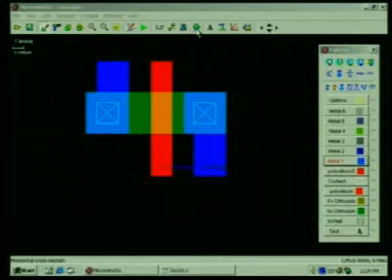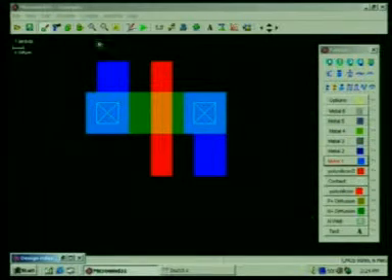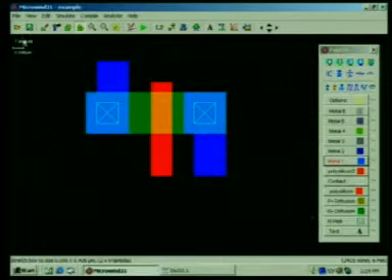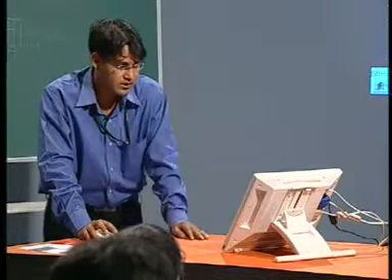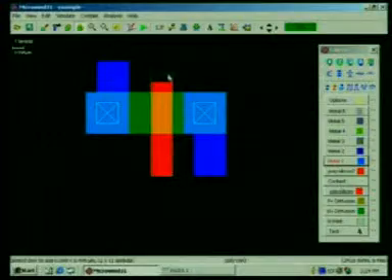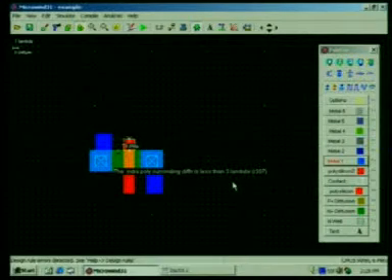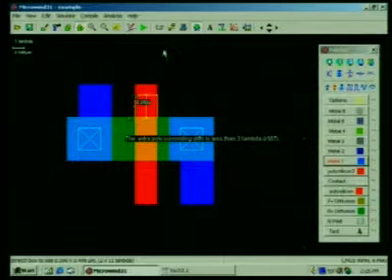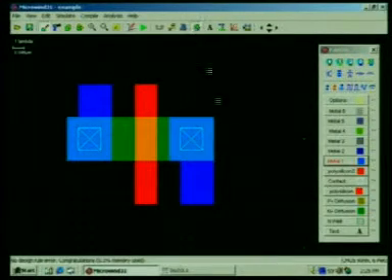And there is one DRC, that is the design rule checker, an online design rule checker. Suppose you have made some mistake, suppose actually this polysilicon should be 2 lambda. See this, lambda shows the distance between these two grids, and this is equal to 2 lambda. So my channel length will be equal to 2 lambda, and they have mentioned already that the polysilicon length should be minimum 2 lambda, okay, and this extension should be at least 3 lambda. Suppose you made only 2 lambda, you just click this, and it will show that error, that it should be at least 3 lambda. It can be more than 3 lambda, but at least that should be 3 lambda. So I will just click this, and now you can again check out.